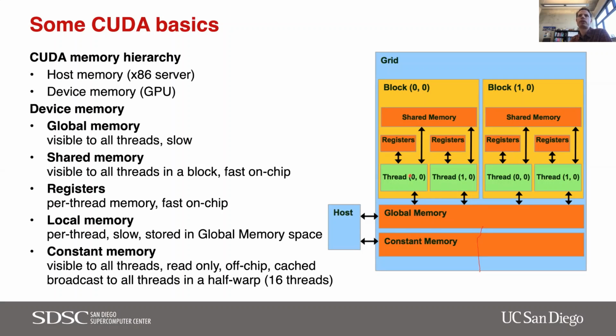The shared memory is actually sitting on the processor where this block of threads executes, and has the same latency as registers. So you really want to use that shared memory to cache data on the chip when you write a program.